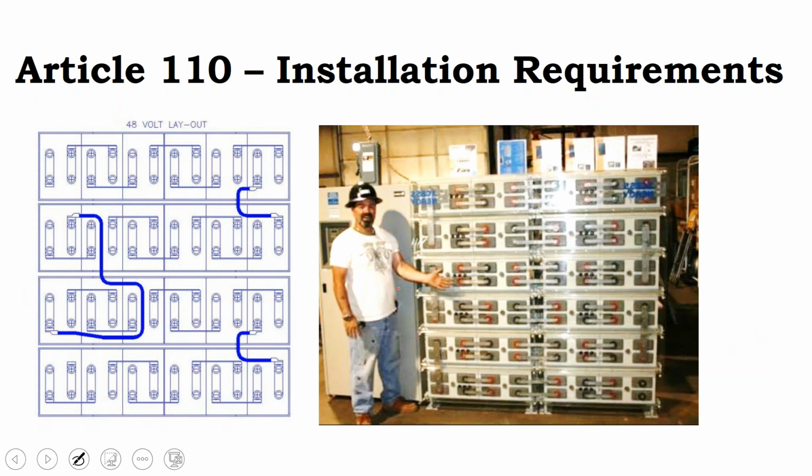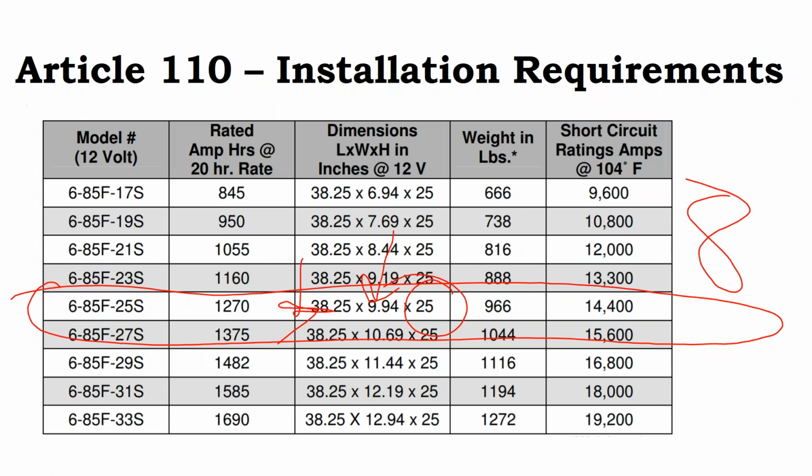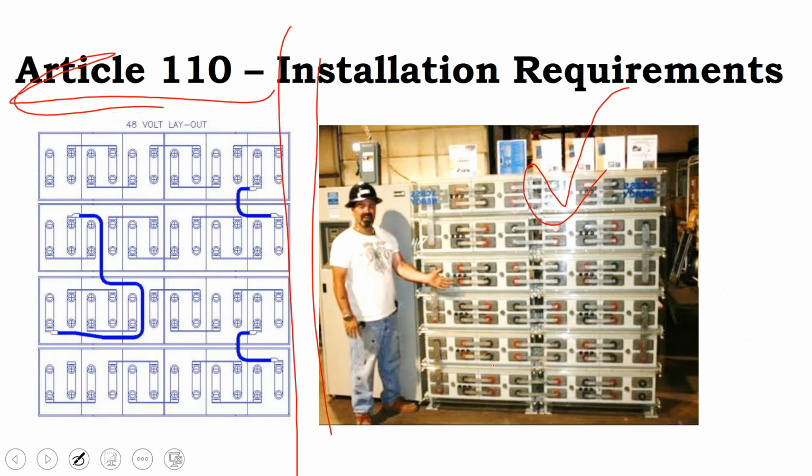And so these are gel batteries that are on the side, but just imagine coming out of the wall. Here's our wall, and we have a battery that sticks out over 3.5 feet. It's 2 feet off the ground. They're heavy as all can be. They weigh 1,000 pounds each, and there are 8 of them. So you have to think about your concrete. 3,000 pound concrete. You might have to actually take a look at that and maybe distribute the weight over a larger surface area. Batteries are heavy. And so we have 8 of these batteries.